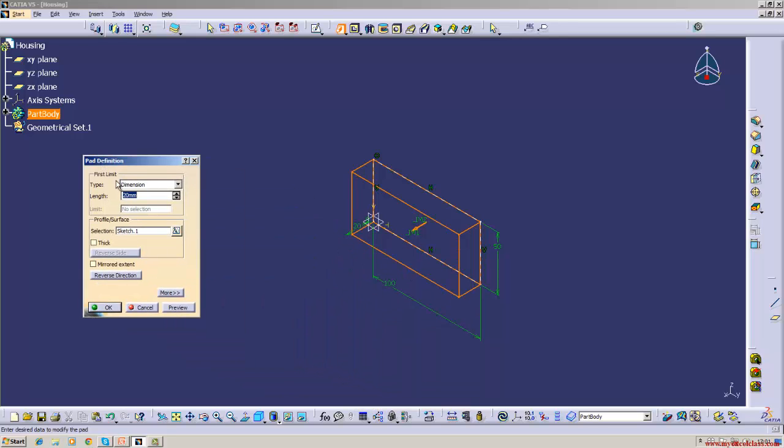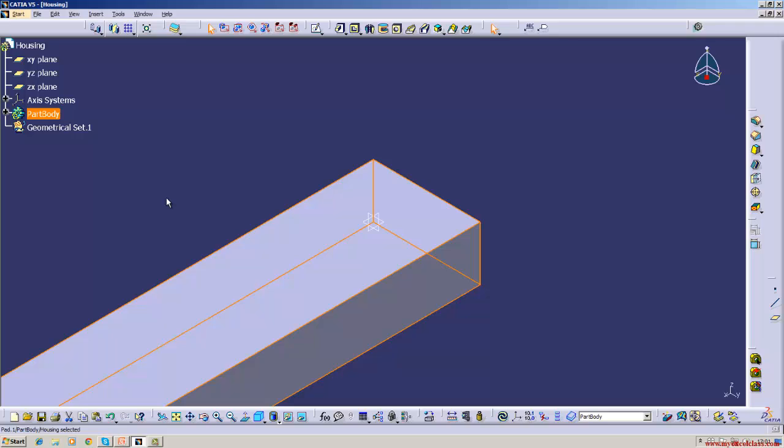Okay, there is green which appears here. The initial default value is 20. In which direction is it? It is towards the zoom outside or zoom inside. The two directions are this way or opposite to this. See, the arrow mark shows it is away from the screen. The opposite is towards the screen. Which direction do you want to extrude it or increase the length? I want to increase the length, say about 500 mm. What you can do, enter 500. It is increased.